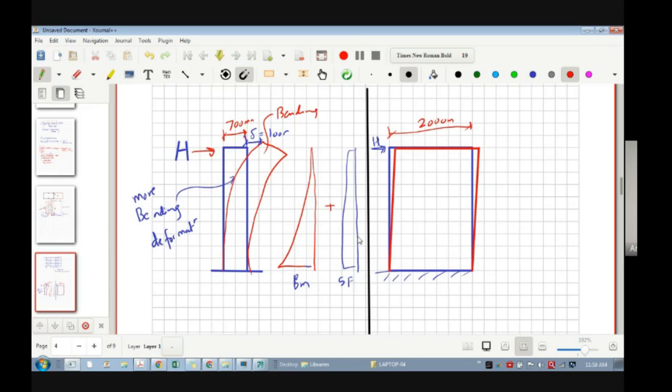That means here there was more bending deformation and therefore more bending moment and less shear force, because bending is more. In this case, there is more shear deformation, which is clear from this. There is no curvature, it is translation like this. Diagonal, we can say. So more shear deformation. Definitely there is a bending, but bending moment is very less, and less bending. Why is it happening? Because this dimension is very large.